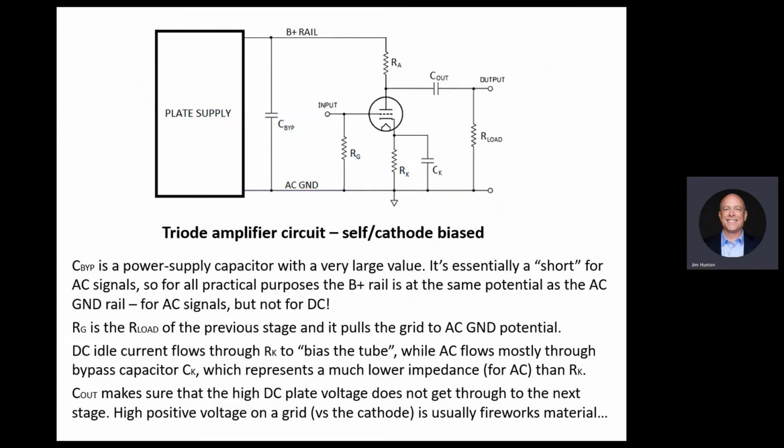The current is developed, signal comes here. The current is developed in this circuit. It falls on this RA, the load, and on this load as well. So from a voltage point of view, both of these loads are seen by the tube. The current splits between them. The tube itself has the internal resistance. The overall effect of that is still higher voltage on the output than voltage on the input. Okay? And the trick was to find the good bias point with what the right current and everything that gives us the lowest noise possible.